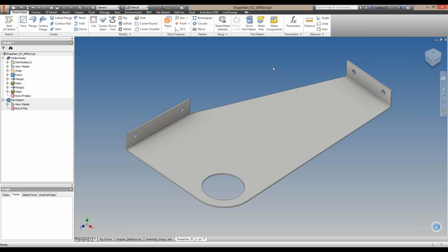design criteria. So I know my areas that have to be fixed. My bolt holes here, those have to be fixed areas. I know my area here is something that's going to be inserted into this and pivot around it, so I know this needs to maintain its shape. But also around here, I know this distance, I really need to maintain this thickness around this part.